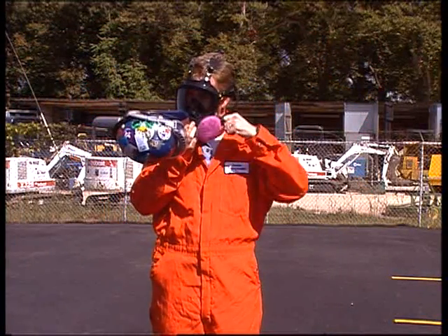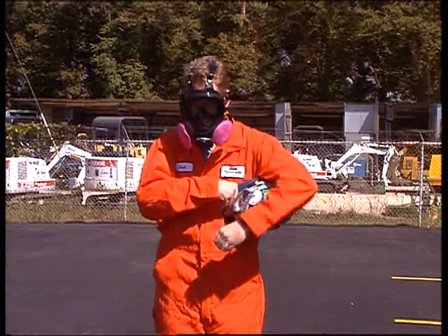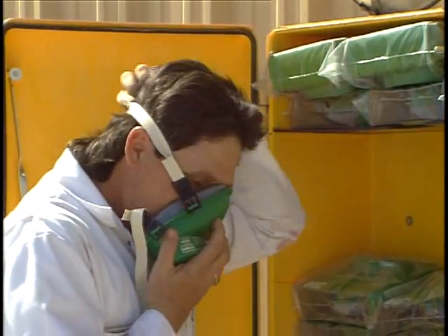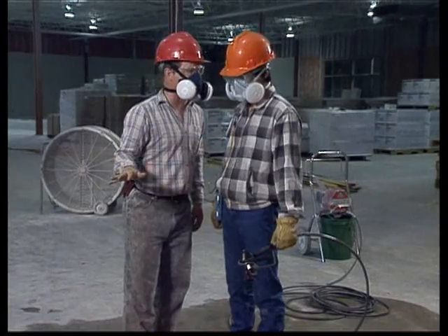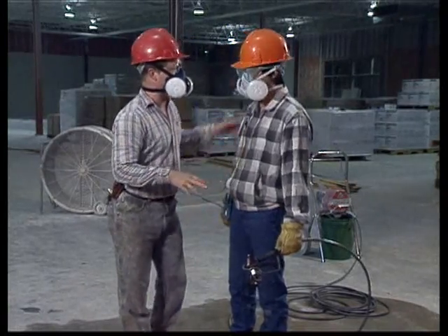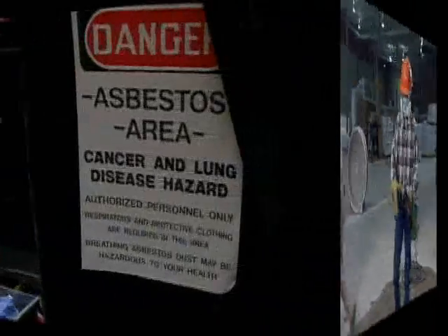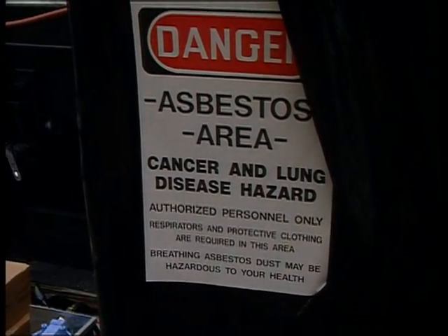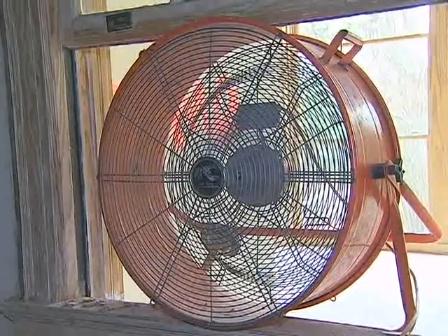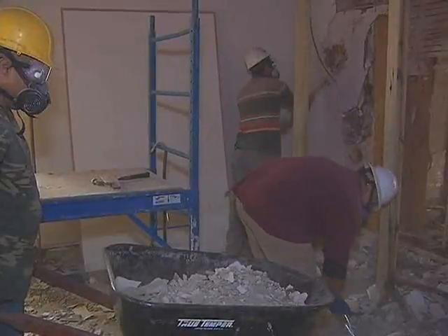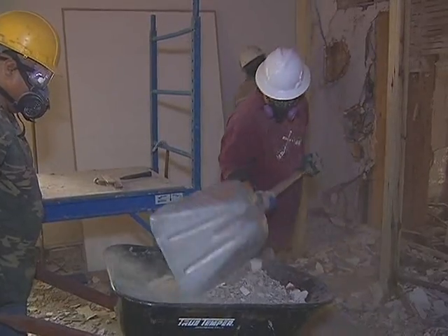Respiratory protection is an important part of PPE. Respirators protect the lungs from atmospheres contaminated with harmful dust, fogs, fumes, mists, gases, smokes, sprays, or vapors. Contaminated atmospheres should always be first prevented by engineering control measures before the use of respirators. Respirator use should always be the last resort.